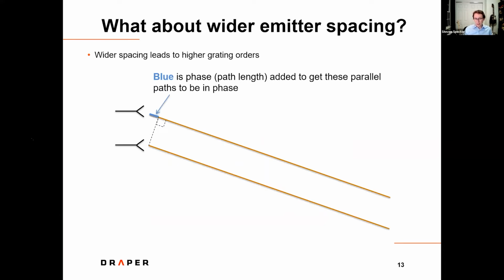Now, as I mentioned before, that picture is sufficient if the elements are less than a wavelength apart, but if they're more than a wavelength apart, it gets a little more complicated. So let's consider the first case now, where we want to point the beam in this direction as shown. So we add a phase so that we have this blue path here. At this point along the dotted line, they're in phase. So the phase of this element is trailing this element here by this blue path. And that means that they're now going to add in phase in this direction.